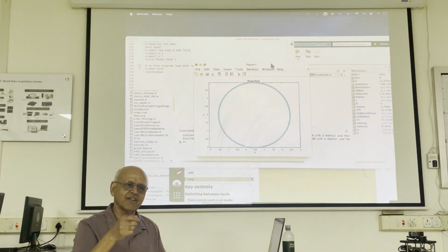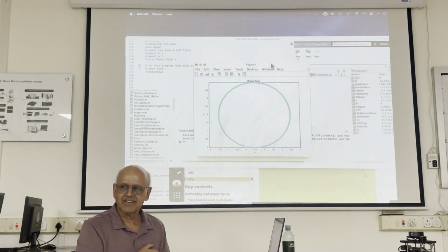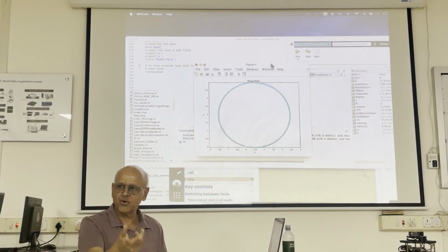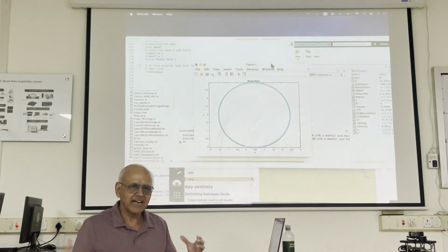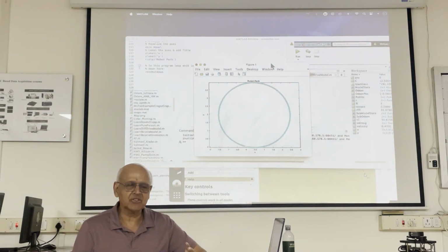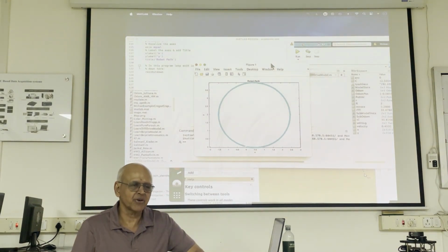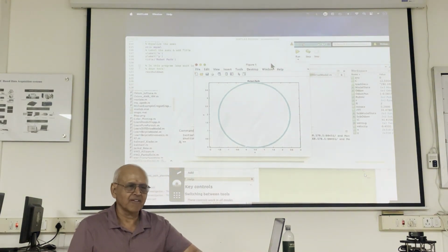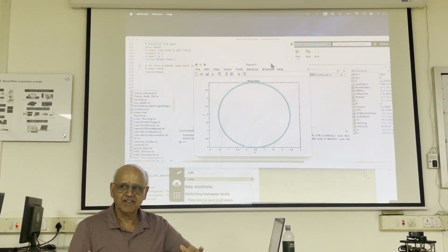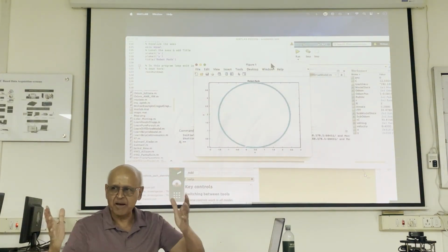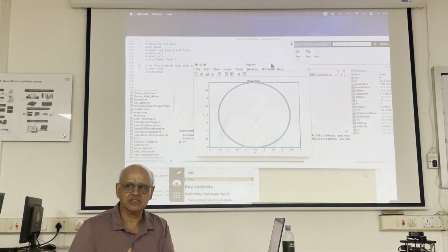That's why you have to have a high-speed sampling unit. LiDAR is quite fast. So you keep eliminating if you don't see it there. If you see it there, you keep augmenting. So that's how a map is created. The map is not 100% certain. Maybe it's 95%, but that's good enough. Because that's how we drive. We see people dashing out from the side of the road, right? And we have a mental map of all that. So we're trying to get a computer to do the same thing.